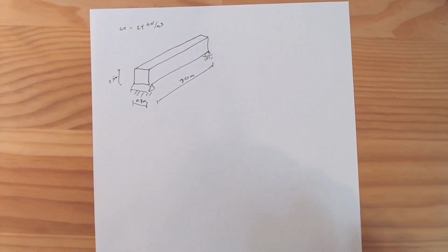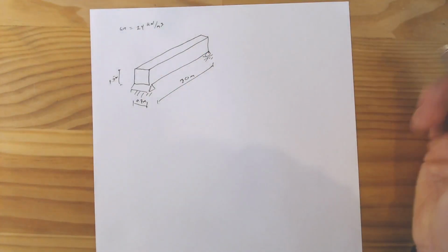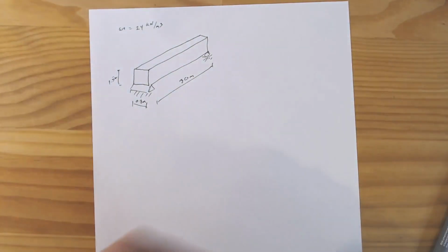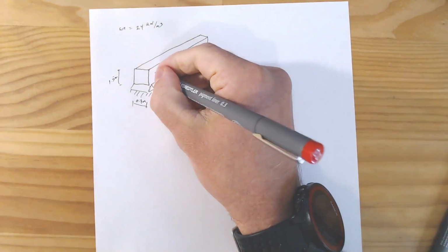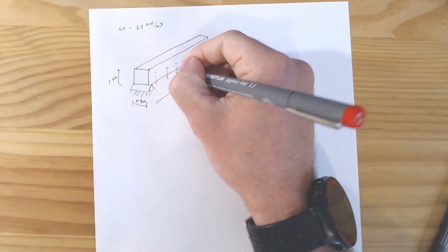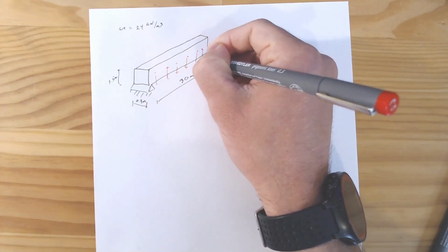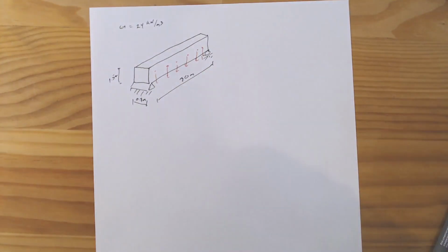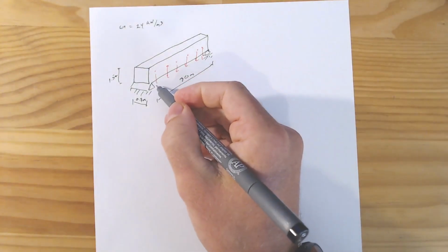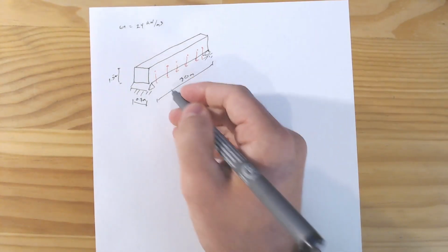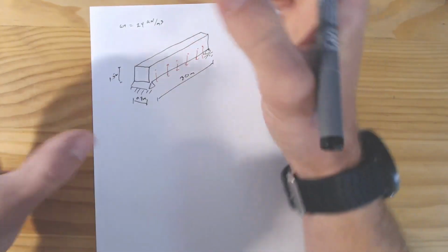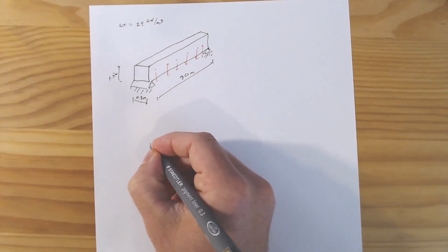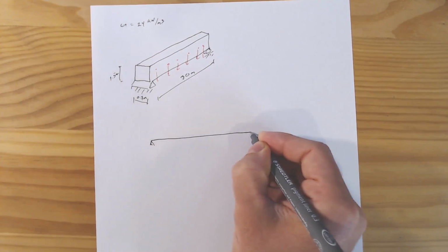Now, we want to draw a free body diagram, so I think what we will do is we'll effectively just start at the end goal, and then we'll just work out what the numbers are. So if we were to analyze this, it has some self-weight, and that self-weight is pushing down just due to gravity. And because this is a uniform section, it's going to have a uniform load. So ultimately what we want to get is a free body diagram between the spans. We know we want to go between the spans because that's the direction that this is trying to bend itself.